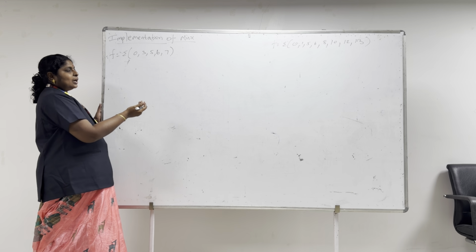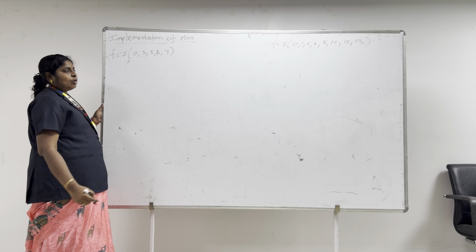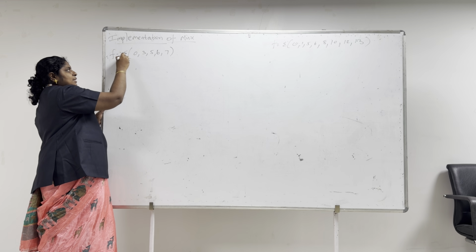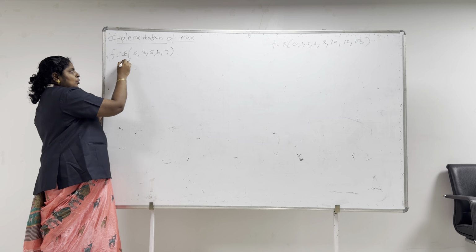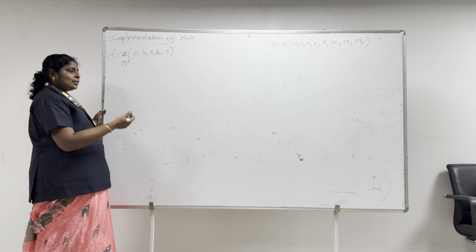This Boolean algebra will be mentioned in the form of an SOP format. So SOP format can be represented as min terms. This summation represents min terms. If the question is asked in max terms, convert that to min terms and then proceed.